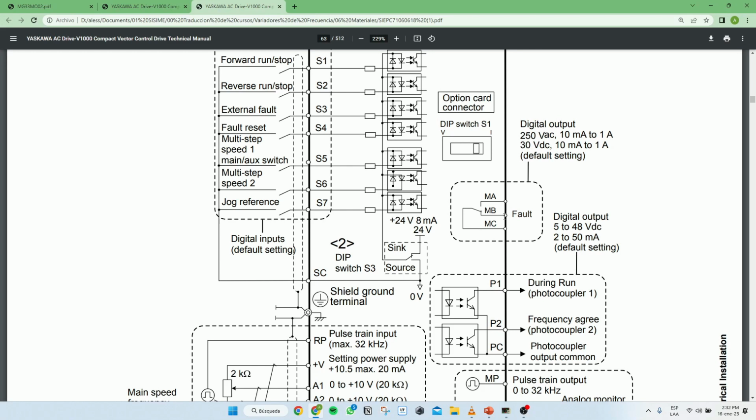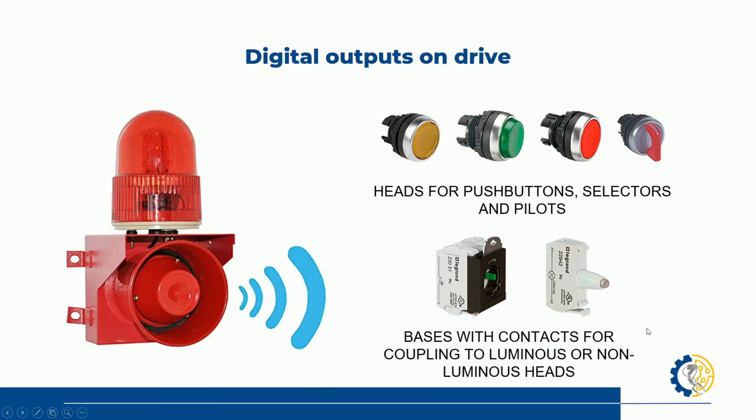Now, what you need to do is interrupt something, because thanks to this interruption, we're going to be able to control that lamp or that output. Let's suppose that on one end, I'm going to connect one phase. And on the other side, so that the circuit closes through the lamp, I would need to connect a neutral, which is 110 VAC.